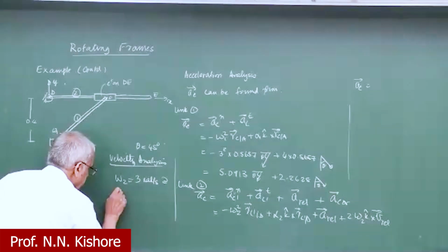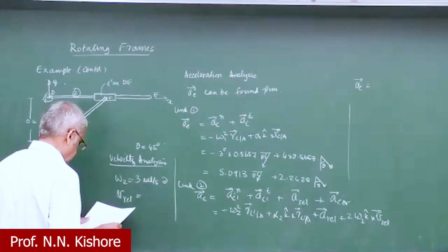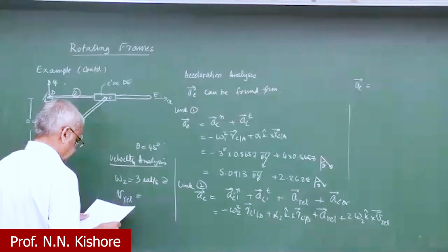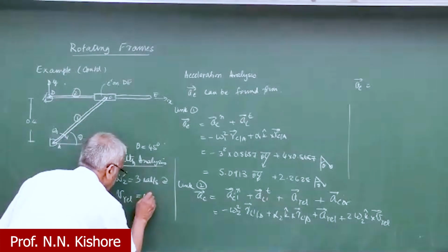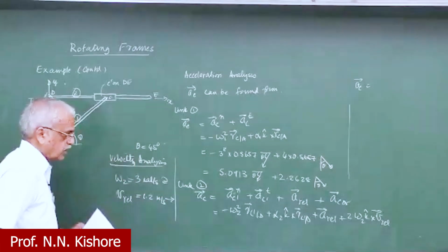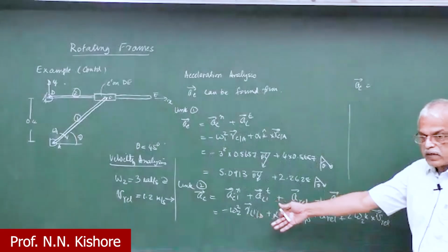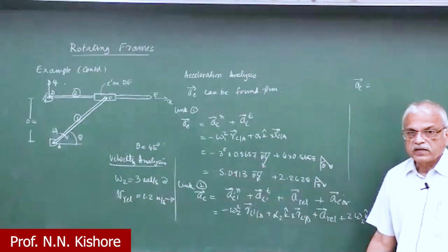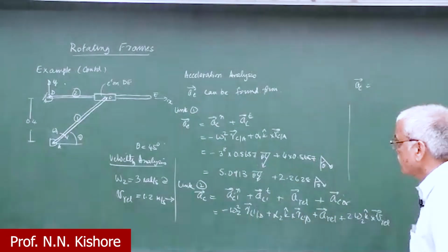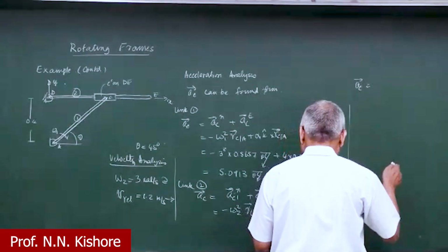So finally, this acceleration of C from this side, we have the first one, the normal component of this C prime, which was on DE. So what is the normal acceleration? That's 3.6. And then the other part, we do not know the tangential acceleration.